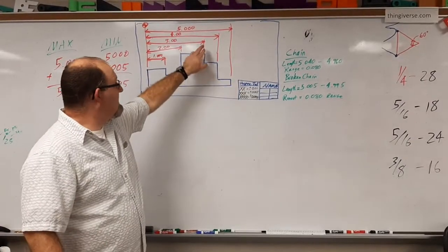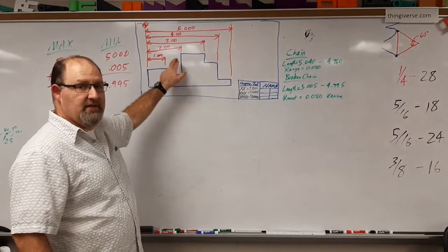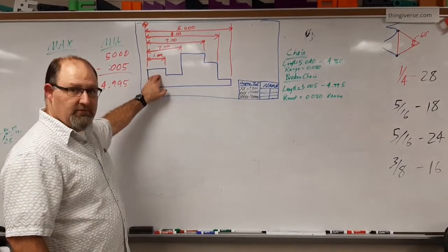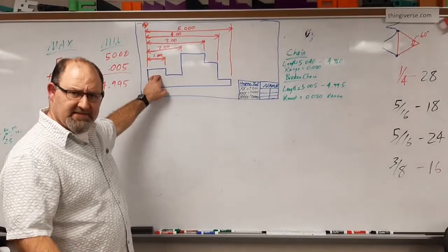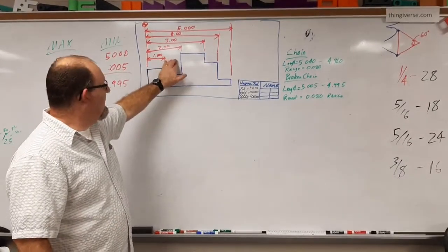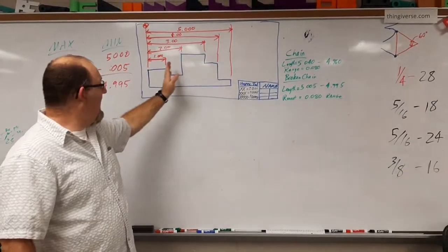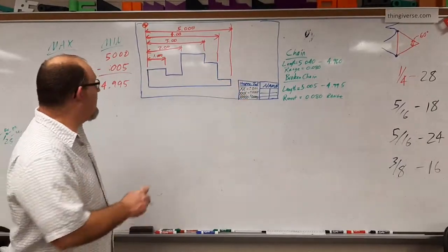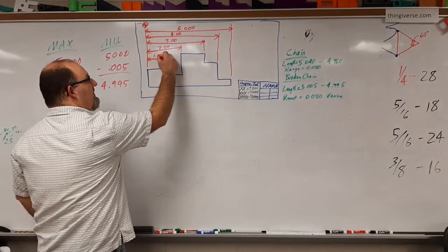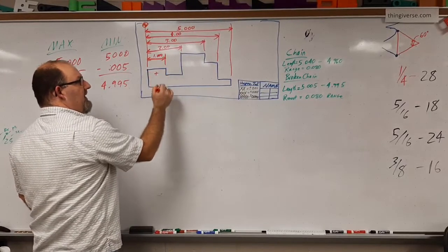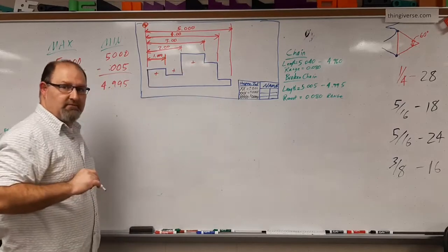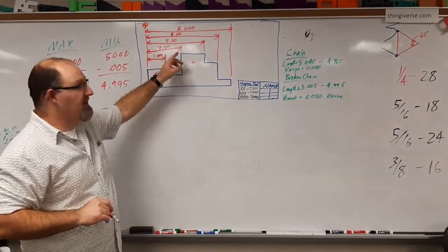The difference, though, is if we were to look at any one of these others, okay? The first one would be unchanged because it's the same as the previous 2 examples. But each one of these now do not have accumulated tolerances. So in both the chain and the broken chain, as we dimensioned, the tolerance from this one would be added to this one, and these 2 would be added to the next one. In this particular case, we no longer have that.